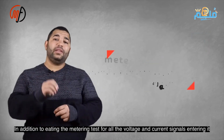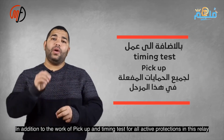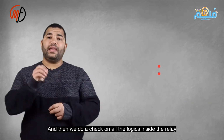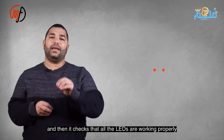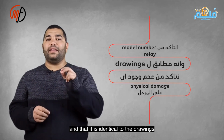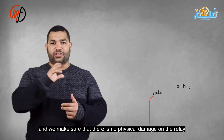In addition to conducting a metering test for all the current and voltage inputs to the relay, we also perform pickup and timing testing for all the protective functions in this relay. Then, we check all the logic inside the relay and ensure that all the LEDs are functioning correctly. Of course, we must not forget to verify that the model number on the relay matches the drawing. We also ensure that there are no physical damages on the relay.